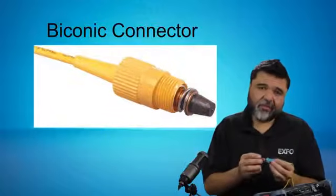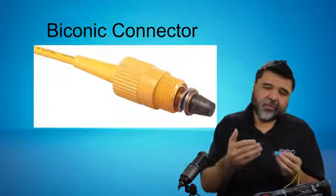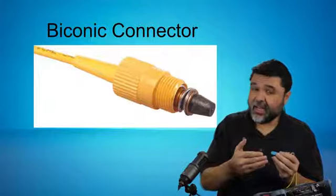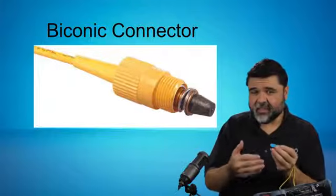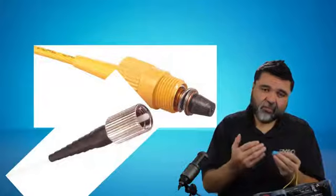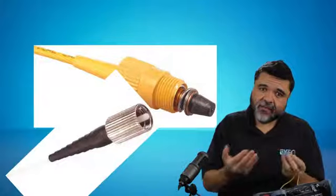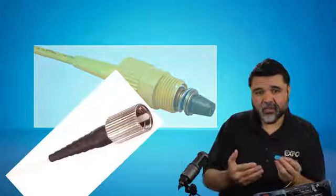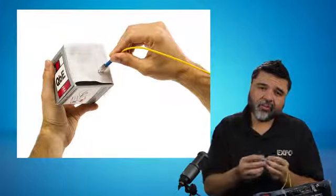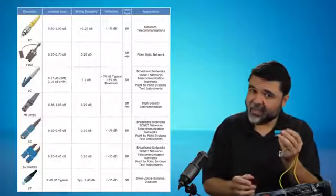And so in that event, you've certainly failed, but at the same time it's important to understand what the specifications of that connector are, because if it is a D4 connector or old biconic connector and you're getting a very high reflection, that's probably spec for that connector. And so you can clean it all day long, it's not going to get any better. So it's important to understand the specifications of the individual connectors.